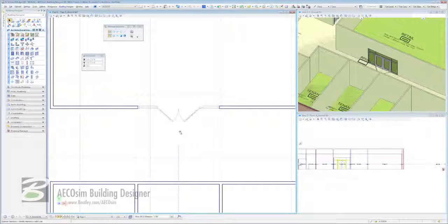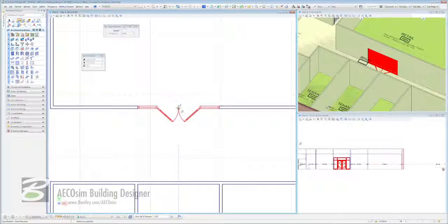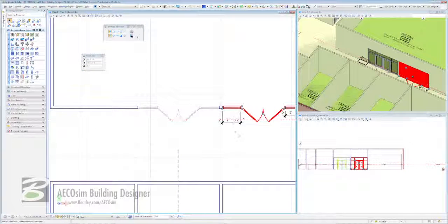Well, quite simply, I can take this door assembly, I can right click on it and say copy, for instance, come to our placement point, which is in the center, and just click once more with our left mouse, move it in a right direction and enter 12 into AccuDraw and click once. And now we have 2 of those door assemblies, as you can see in your isometric, side by side, ready and roaring to go.